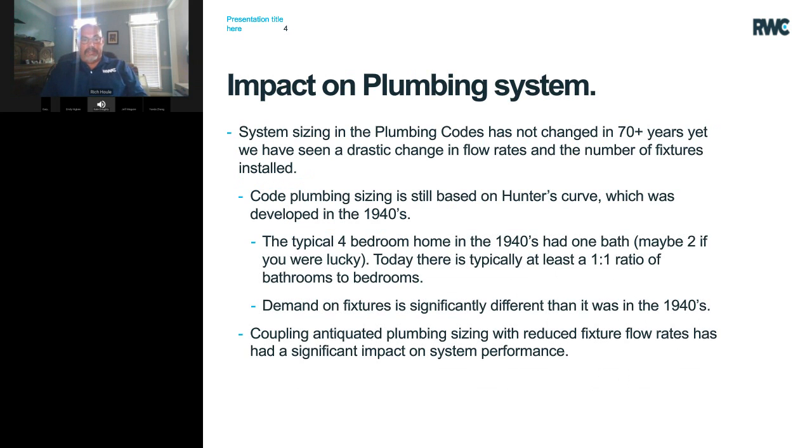When we look at the impacts on sizing, our system sizing in the UPC, short of Appendix M, and the IPC, they date back 70-plus years. And we've seen a drastic reduction in fixture flow rate as well as how buildings are designed today. The code plumbing sizing is based on Hunter's curve, which was developed in the 1940s. And if you think back to the 1940s, not a lot of us were around. There's a few of us, but not a lot.